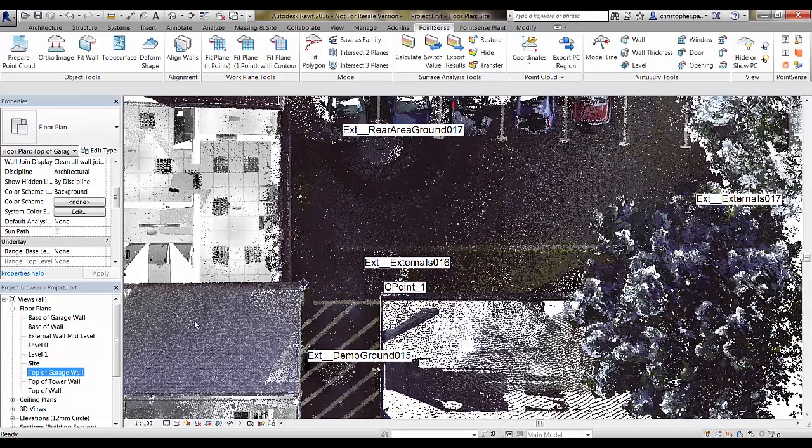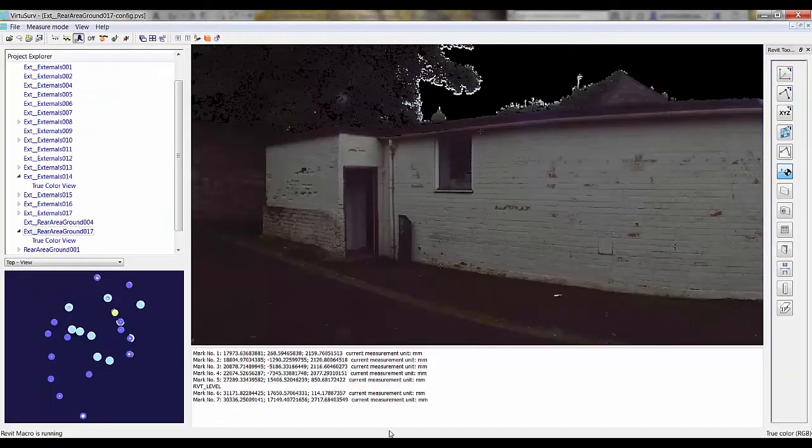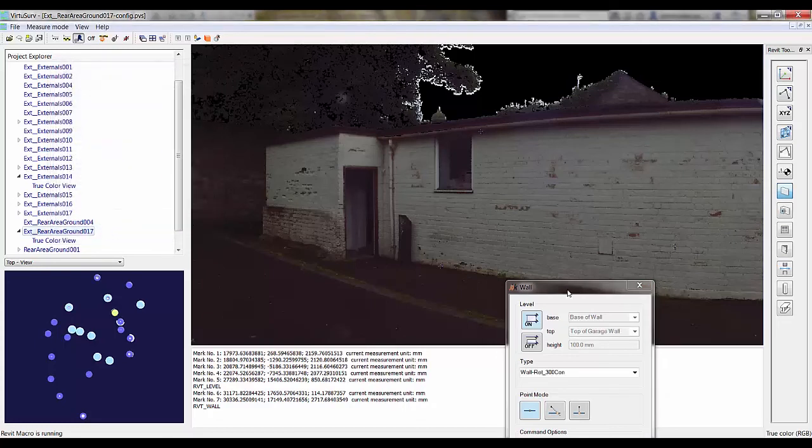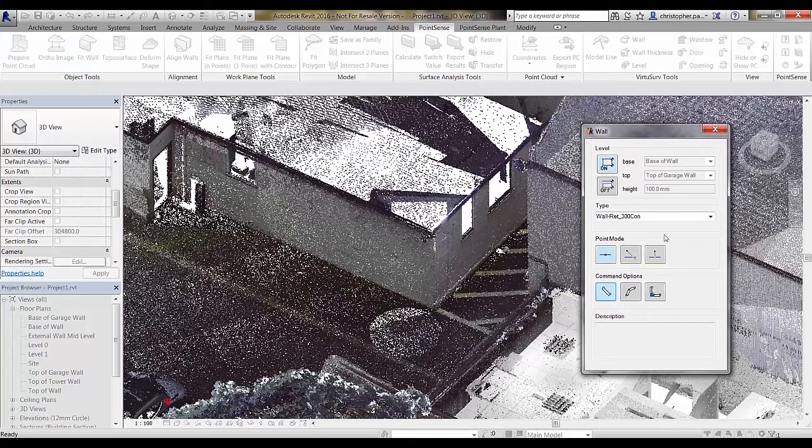As I've got quite a few intermediate levels now in the project, it's probably worth naming those, and when we insert this wall, we're actually going to turn the auto level off, I think, in this instance. So yeah, there we are. Just turn off the auto level.